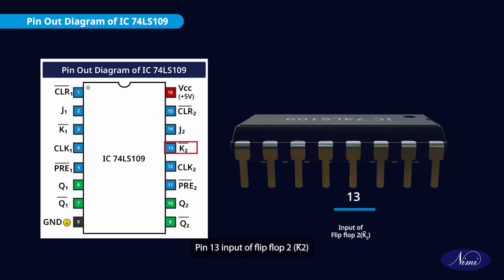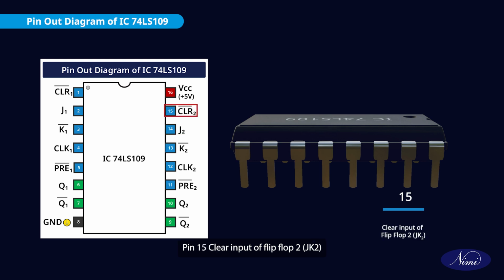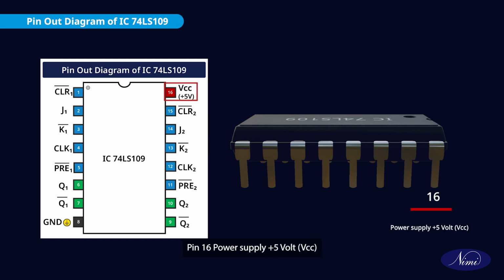Pin 13, input of flip-flop 2 K2. Pin 14, input of flip-flop 2 J2. Pin 15, clear input of flip-flop 2 JK2. Pin 16, power supply plus 5V VCC.